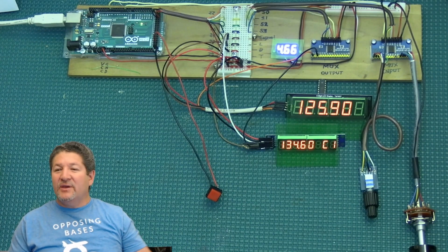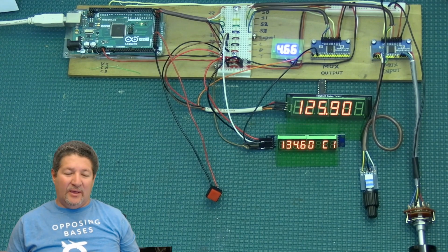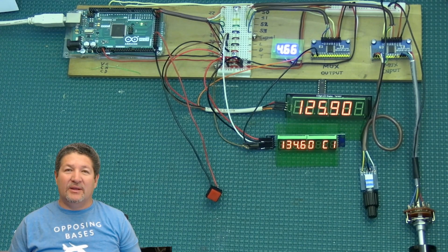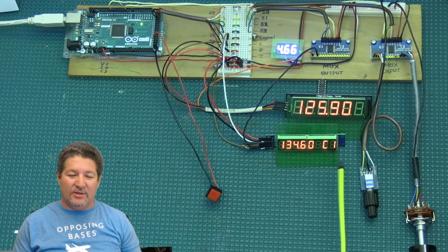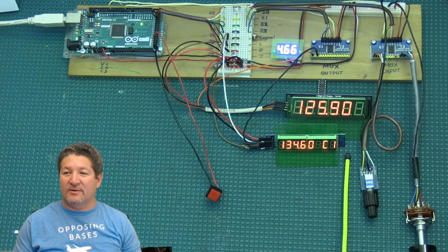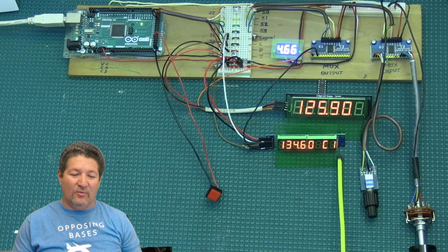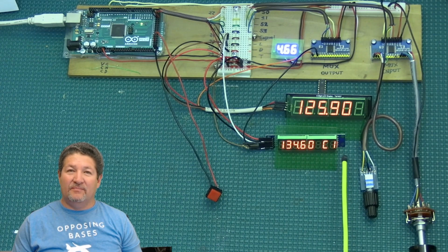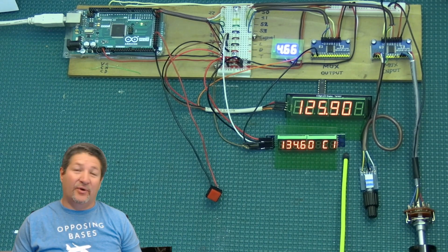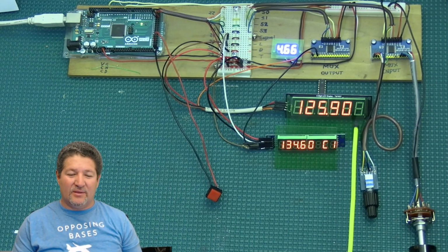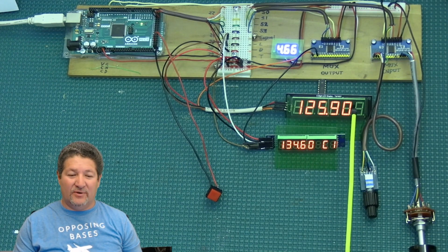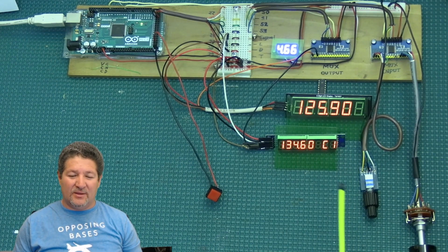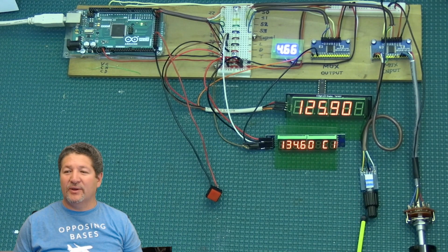Okay, so I have here on my table the little setup that I made. We're going to use this display right here, the Max 7219, and make it do the standby frequencies for all four radios. This is going to be the active frequencies for all four radios, and this is going to be the rotary. It's a dual rotary encoder, so we can tune the megahertz and the kilohertz for all four of them.